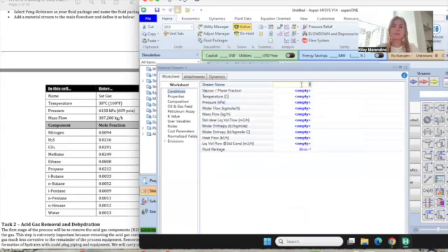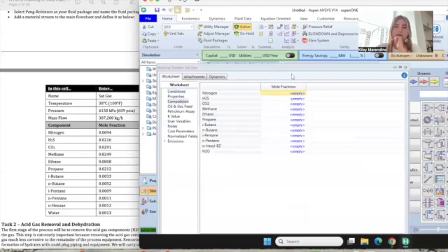Up here, the name, we can click on it once and type sat gas. We're given the temperature, 38 degrees C. Pressure, we have 6150 kPa. Mass flow, which we want to make sure we're in mass and not molar, is going to be 387,200, and make sure you have the right units, kilograms per hour. Then next, we're going to head into composition, and this will allow us to do the mole fraction. You can also do mass fractions.